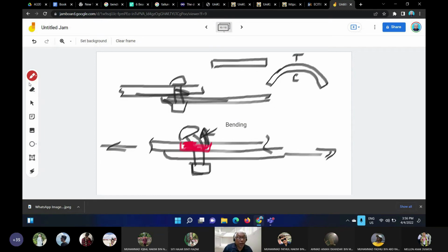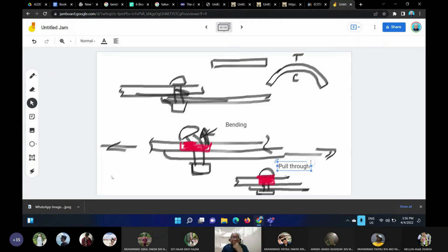So in other words, if we have a plate and plate, you have the reverse head here, you have the shank here, you have this formed head here after you work the backing bar. So the failure under the head here, that is what we call pull through. And you need to calculate that.